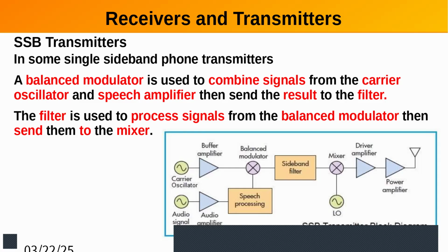In generating single sideband, particularly if it's an analog radio, they'll use a balanced modulator or a double balanced modulator. You buy those from Mini-Circuits in little packages. You don't have to make them. And you combine the signals and get out the sidebands, and then get rid of one of them so that you can transmit it. And then usually they'll have another mixer there to shift the frequency up from the initial.